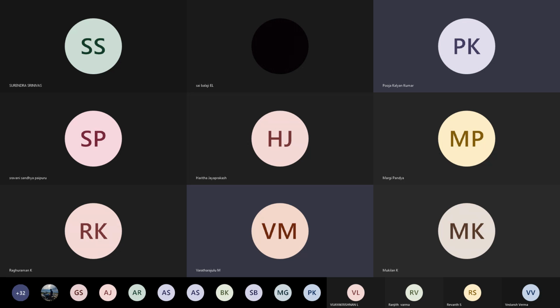The next one is the gated pattern. It's usually used in mass production. Here, the mold cavities are formed in a single mold by joining many mold cavities together using a common gate and riser system. That's why it's called a gated pattern.